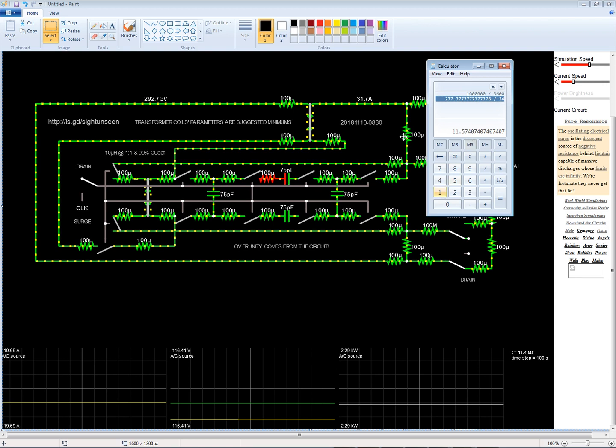So if you multiply by 10, because that's what we actually have down here, that's actually not 2 weeks. That's actually 20 weeks, which divided by 4 weeks in a month is 5 months. You got to wait 5 months to see a 4% drop of an amp if you're putting 20 amps back onto the grid non-stop.